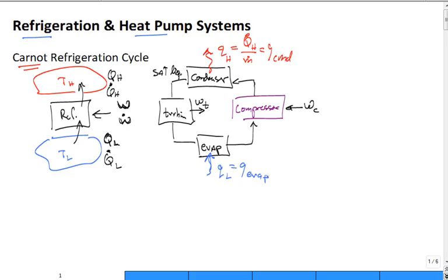So you get the perspective of what's happening to the fluid inside of either of those heat exchangers. The evaporator, the fluid's evaporating, going into the vapor phase. It makes sense. And in the condenser, what's happening to the refrigerant? It's going into the liquid phase. It's condensing as it flows through the condenser. I know that can be tricky at times, but go slow as you begin the study here. So let's do a first law analysis for the compressor.